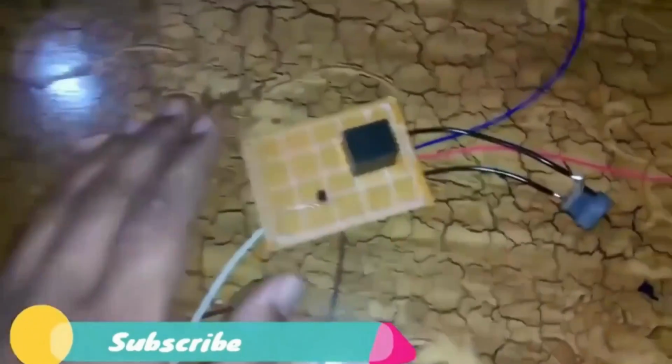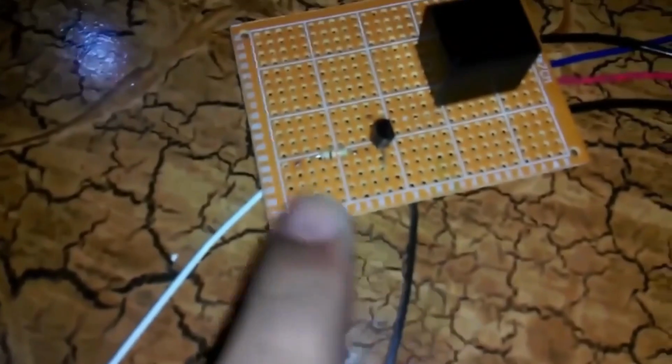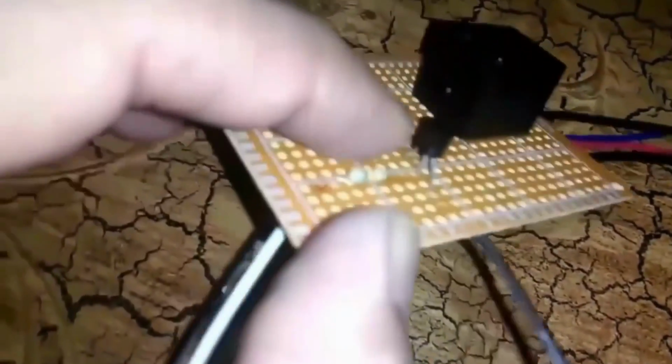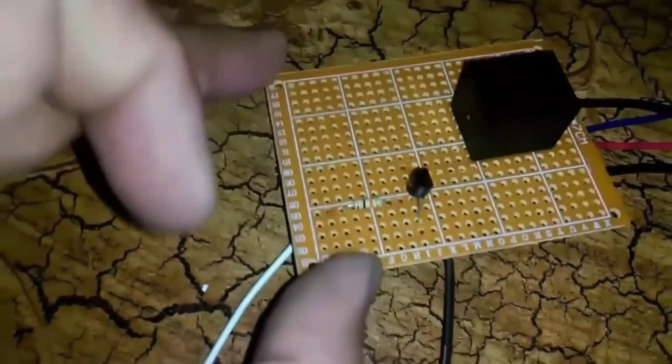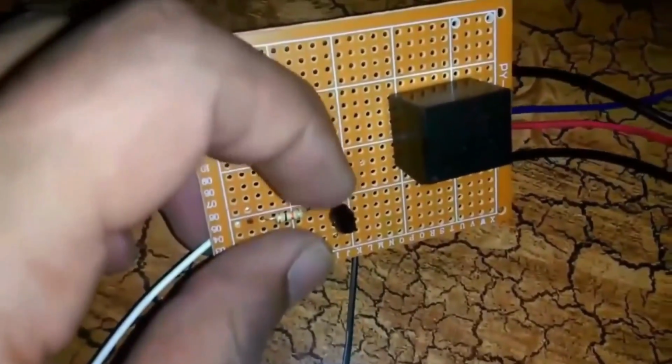Okay, now all the wires are connected. This is a 10K resistor which is connected with the base of the 2N2222 transistor, and this is the emitter, and this one is the collector.